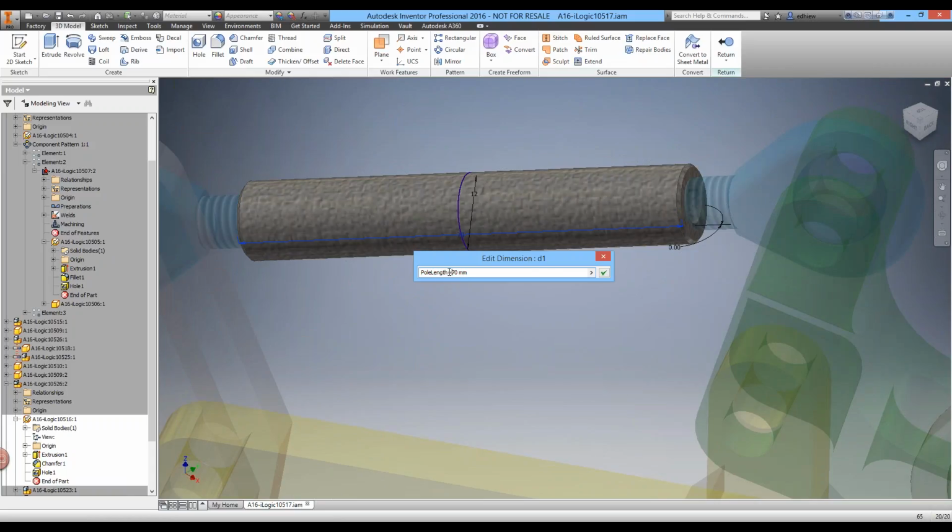equals. Okay, just keep in mind when you're renaming parameters, make sure that you don't put spaces within the variable name. That's not allowed. You could put underscores in between. I prefer what's called camel case, where you start each word with a new capital letter. That's how a lot of programmers create their variables. And there's no issue with white space around the equal sign. It doesn't matter.